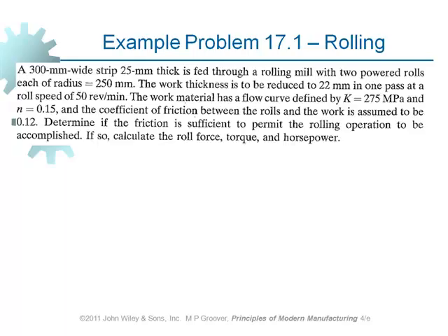If material is being subjected to hot rolling, meaning that the temperature of the operation is above recrystallization temperature, this n should be equal to 0. This n is telling us how much harder material becomes after it is subjected to deformation. Above recrystallization, material does not become harder, meaning that the slope is 0.